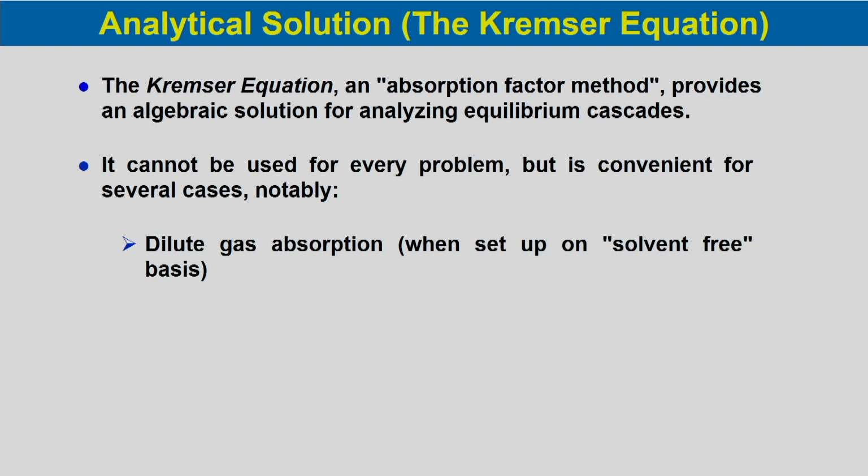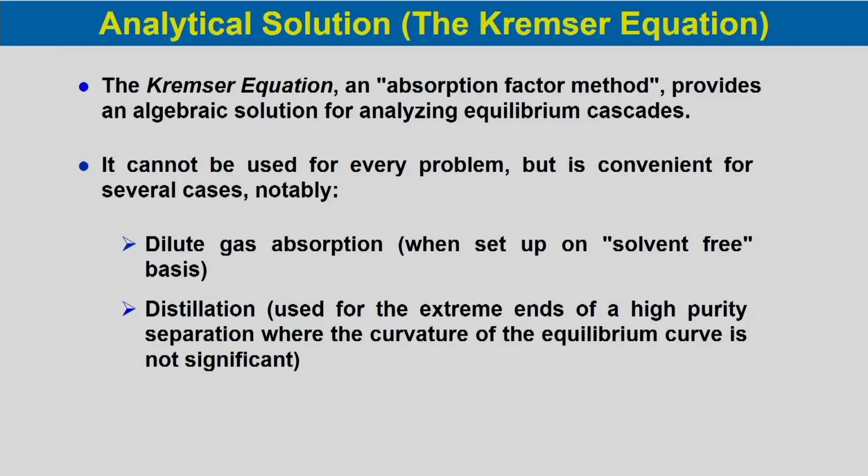So, if it is dilute gas absorption, the change of molar flow rate of gas or liquid after the contacting process is very small. The solute transfer from the gas phase to the liquid phase, or in the other case from the liquid phase to the gas phase, is small, and in that case we can use this Kremser equation.